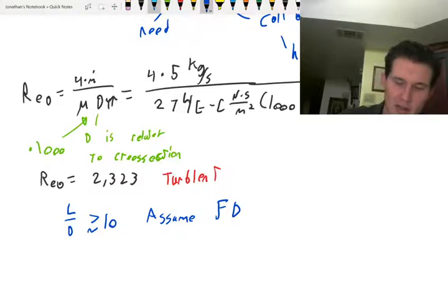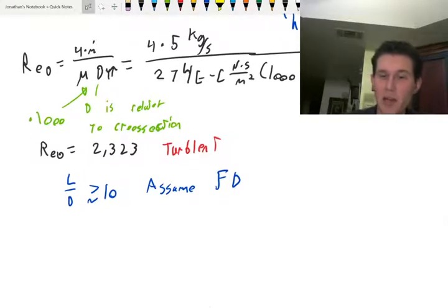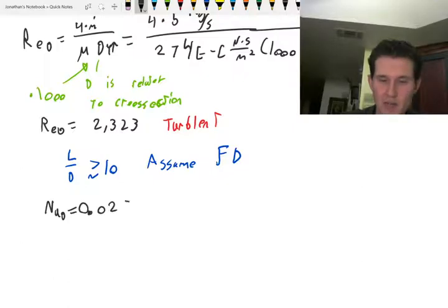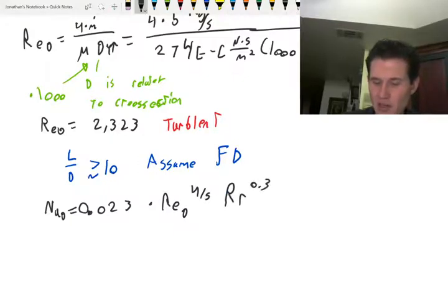So now we are not going to mess with the entry region equations, and we're going to make our lives easier. Now let's go ahead and get that internal convection coefficient, h_i. I want to make my life easy. So we want to calculate that Nusselt number. Remember, you have to calculate your Nusselt number to get your h_i. It's going to be nice and quick and beautiful, and we're going to be done here in just a moment. And there were some conditions on this equation. If I remember right, there was a condition.